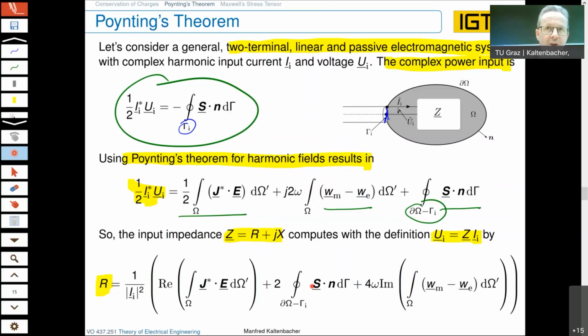At some distance where we are at the far field, it is also called the radiation resistance you have of your antenna is pure real. In the near field, you will always have also reactive parts, and energy is going forward, backward. And what is really radiated at the end, these waves which are radiated and you can receive in the far field, will be pure real.